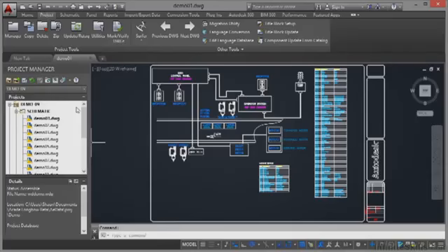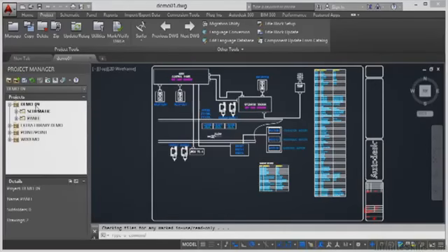Quite often when you're working with an AutoCAD Electrical project, you need to group the drawings. Now you'll notice over in the Demo 09 project here in the project manager that we've got two subfolders. We have a schematic subfolder and a panel subfolder. The schematic subfolder is for the schematic drawings, the panel subfolder is for the panel drawings in the Demo 09 project. Now it may be that I need to create another schematic folder for use with other schematic drawings.